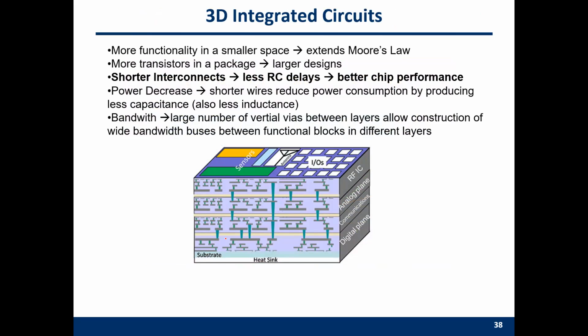So one simple solution for all these disadvantages of FPGA boards, long wires, and 2D process technology is the emergent 3D integrated circuit. Besides one active device layer, we can add more active layers in the vertical direction. We can stack multiple digital parts, analog parts, communication parts, even your connection, into a 3D structure.